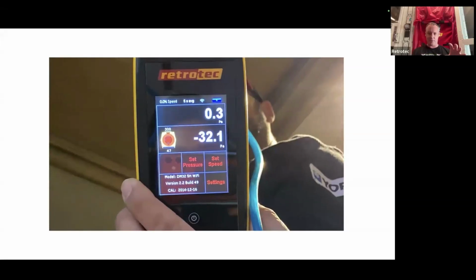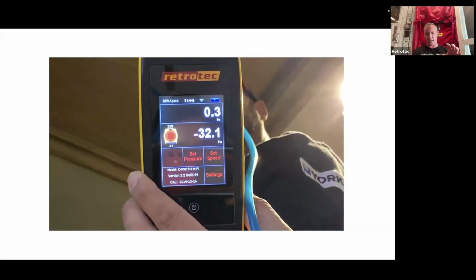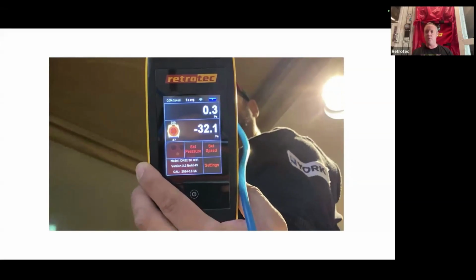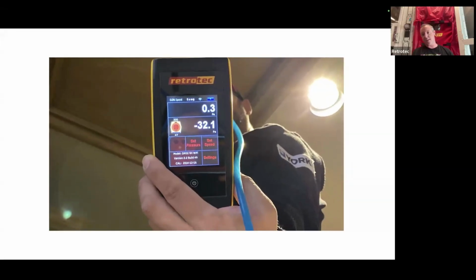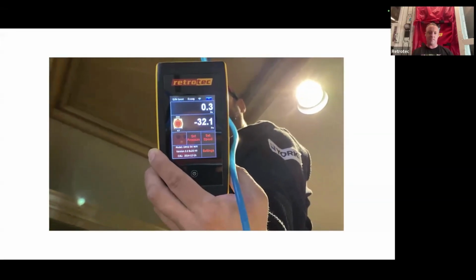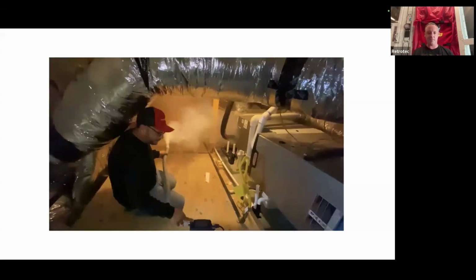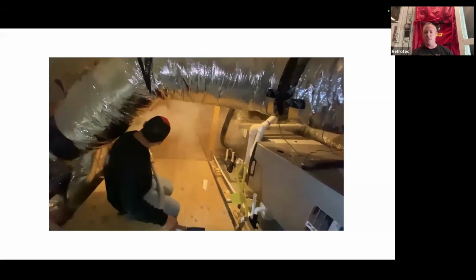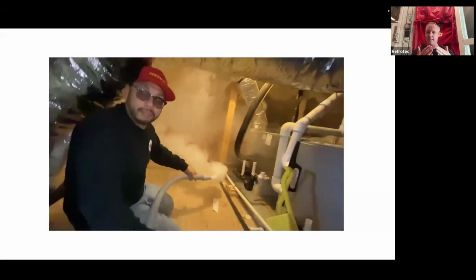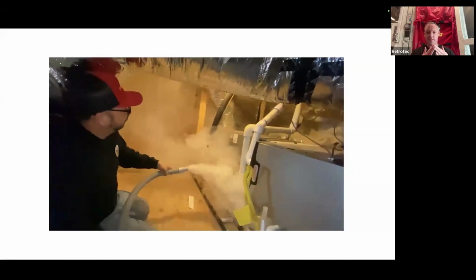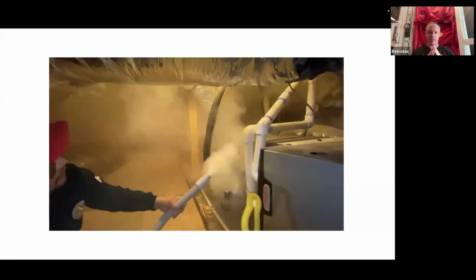So that attic has been encapsulated with spray foam. So it really shouldn't be pushing that much fog into the rooms. And we're pressurizing. So as we pressurize and push that smoke, it's going to go towards the leaks. He also did some zonal pressure diagnostics. We'll talk about that in a minute. But then to really prove, like, okay, we can see that it's leaky, but let's really dial it in and see where those leaks are occurring.